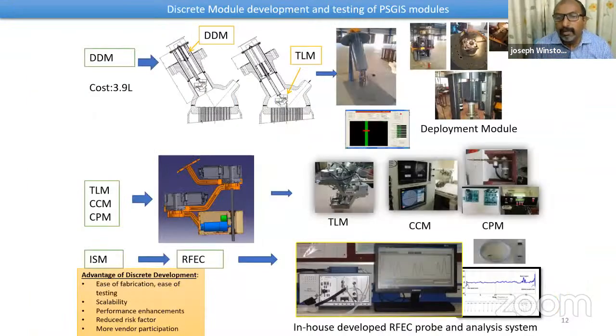So this is how we design the system. Here you can see it is a simple mechanical system with a ball screw arrangement at the center, and there are LM slides, linear motion slides, on the side, which support the deployment system for accuracy. On top, there is a motor running this ball screw, which causes the forward motion of the deployment and pushes the robotic system into the header. That is done by the deployment system.